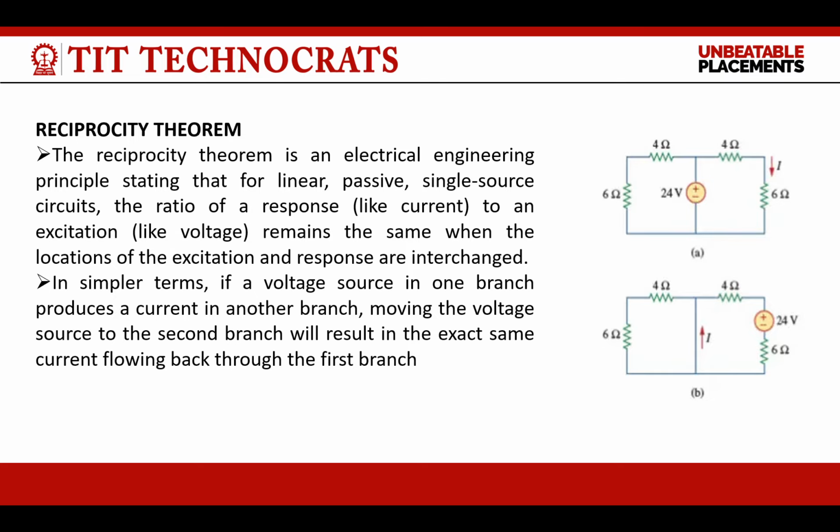Reciprocity theorem. The reciprocity theorem is an electrical engineering principle stating that for a linear passive single source circuit, the ratio of its response to an excitation remains the same when the location of the excitation and response are interchanged. In simpler terms, if a voltage source in one branch produces a current in another branch, moving the voltage source to the second branch will result in the exact same current flowing back through the first branch.